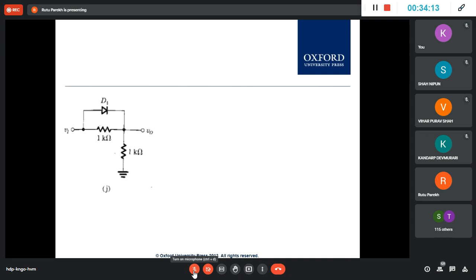Okay. So when it is an ideal diode model, and when you have a positive half, this is like a wire here. Current can pass through this, but it has two paths, so whichever is easy, we take that. Now the road which is easy to walk, we will take. So here also it will take the easy path. So for the positive half, it will take this path. It will not go through this, because this has resistance. Here there is almost zero resistance. Understood? Or let's say if the diode in reality has resistance, but it is in a few ohms.